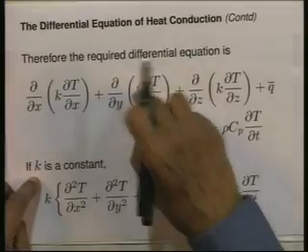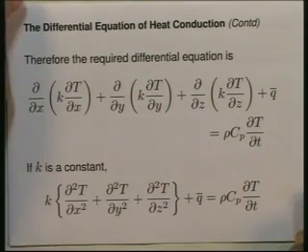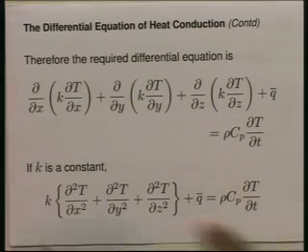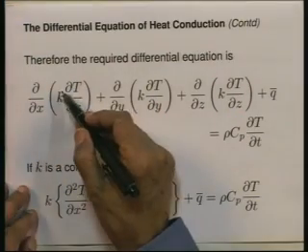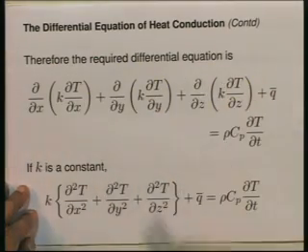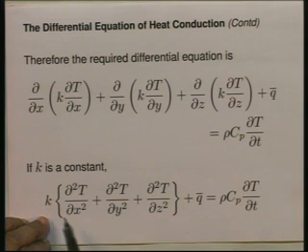All right. Now, let us look at some simplifications of this differential equation. We say to ourselves, suppose the thermal conductivity K of the material is not varying from point to point inside the material. That means K is a constant, the material is what we call homogeneous, in which case the K can be taken outside the differential here, and we will get the differential equation which is written here.